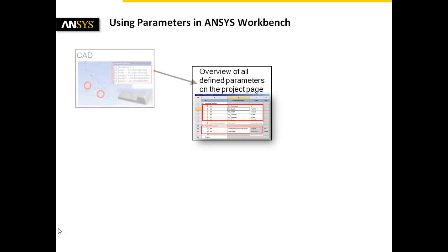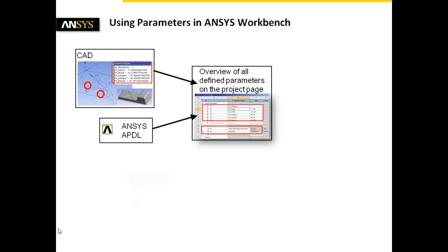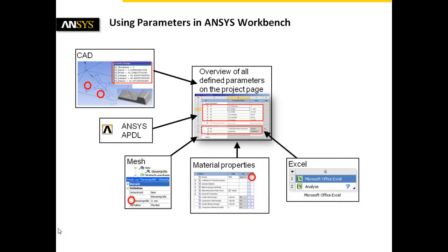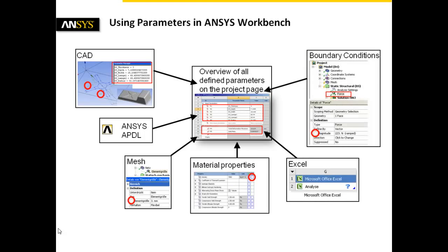They can be defined in the CAD system, as an ANSYS Mechanical APDL parameter, as a meshing size parameter, or a material property. Moreover, parameters can be imported from an Excel sheet, or they can be defined within the simulation environment with respect to boundary conditions or result objects.